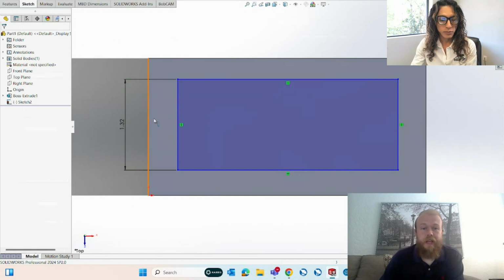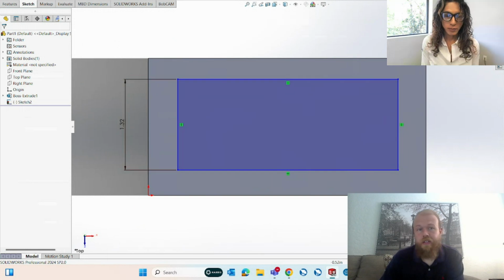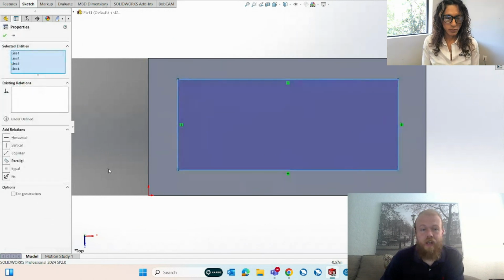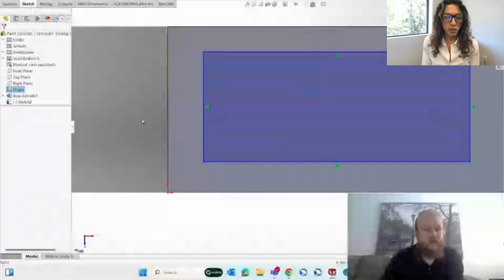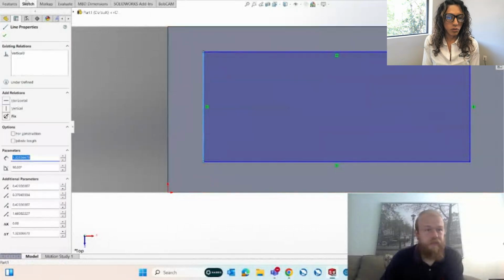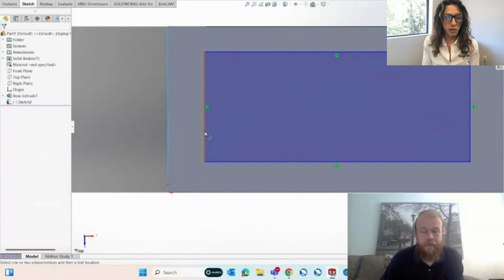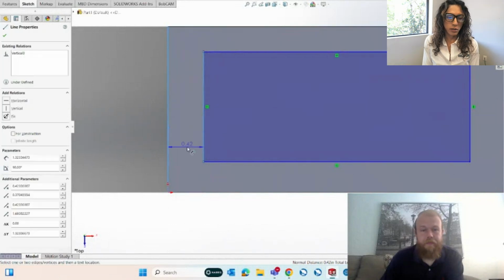Yeah, absolutely. So we have our dimension of the rectangle here. I'm just going to hit undo once up at the top, and I can change the dimensions from the actual rectangle here to maybe the corner of the original rectangle. You can do it to the side, so it's from the center to side. Sure, yeah, like side to side here. So you're thinking go to smart dimension, and then pick center and center? Yeah. So it always will be that distance between those two.